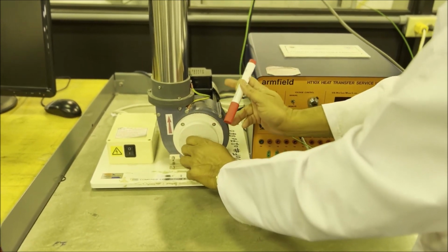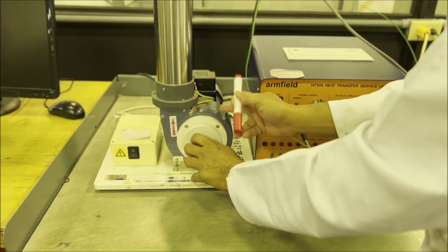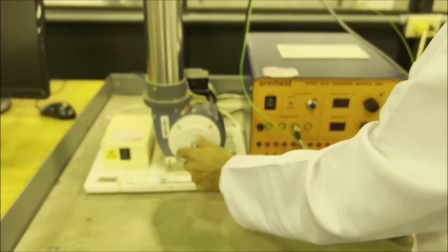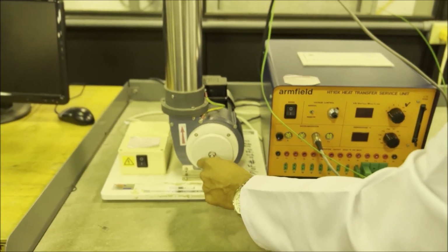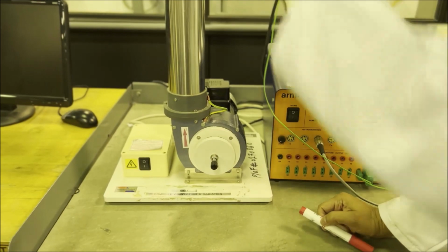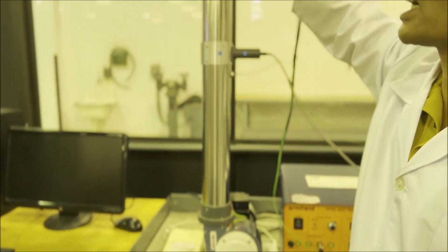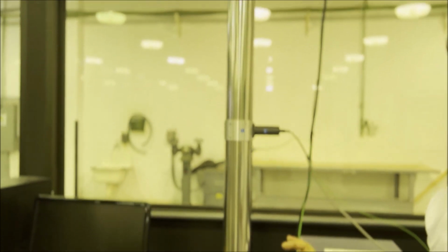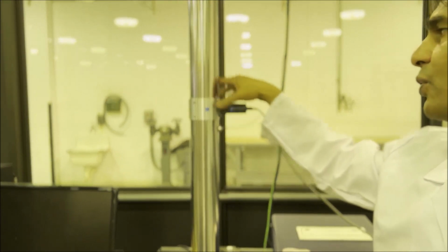There is a fan, but we are not going to operate the fan. Next week we are going to operate the fan for forced convection. Today is free convection, so as a first step we need to make sure this is open so that outside air will go inside and this hot air will go outside. Because of the density difference, the air will start flowing over this cylinder naturally.